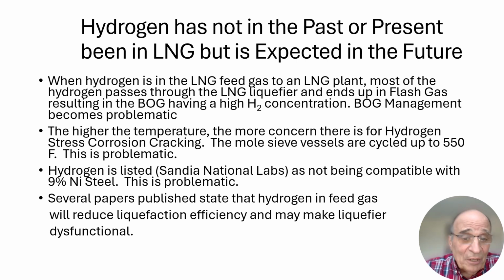Several papers have been published that state hydrogen in feed gas will reduce liquefaction efficiency and maybe even make liquefiers dysfunctional. So there may need to be hydrogen removal systems upstream and within the liquefaction plants of today.